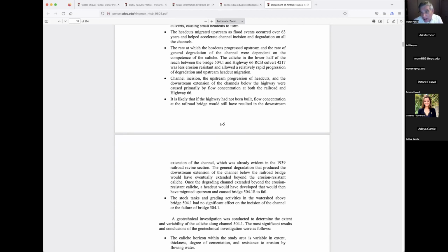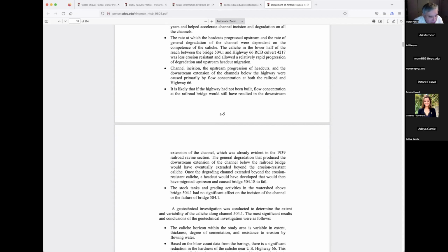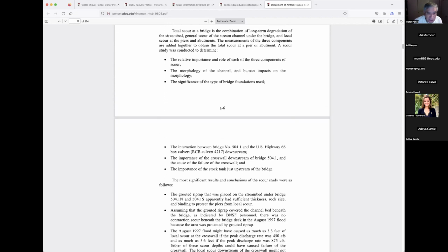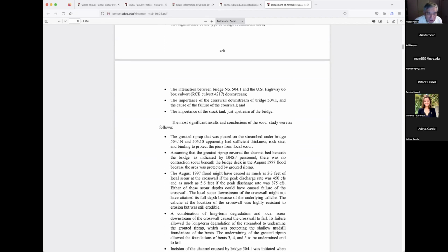Why is it luck? Because what happened was, obviously, from my experience, that at 8 o'clock, nothing had happened. But by 11, 3 hours later, something was happening at that bridge. It had settled. How much? A few inches, but enough to derail, because the train is not good with some change in the grade. Even a minor change in the grade will still derail the train, as it happened over here. Okay, so I'm going to proceed with this.